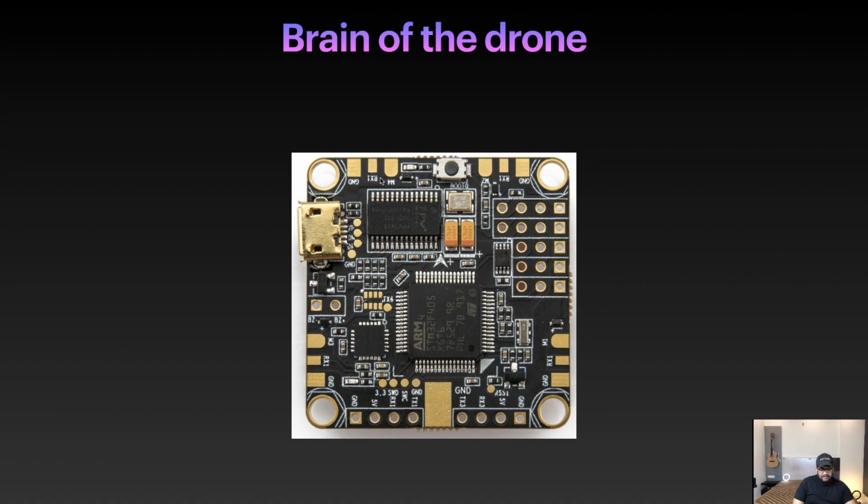You can see that over here, these are the pads where you solder the ESC wires, where your flight controller and ESC will communicate. So these are the solder pads where you can solder the signal wire of your ESC. And over here you can see ground, 5 volt, RX and TX. These are the UARTs, and here you can solder the receiver. If your receiver works on S.Bus, it uses a UART for the communication. UART is a serial communication protocol, universal asynchronous receiver transmitter, and over here you plug the receiver.